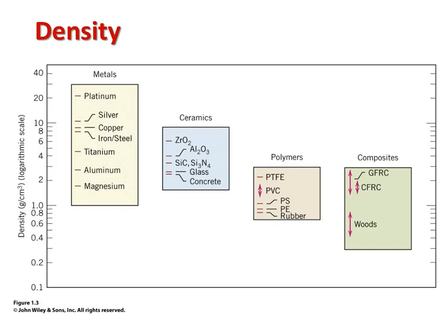And as a caveat, magnesium alloys definitely are problematic from an incendiary standpoint, and from the standpoint of strong materials that you can use in most service applications, they are definitely the lowest density metals you can get. So this is a pretty generous range for the metals category.